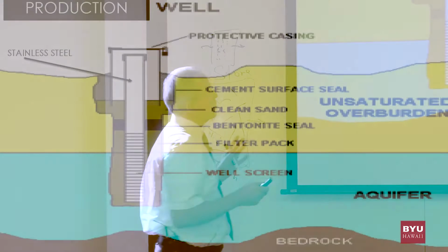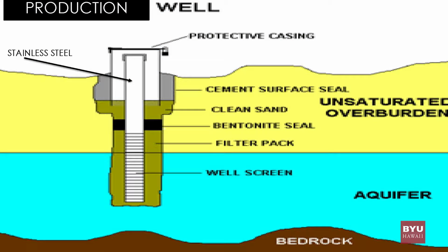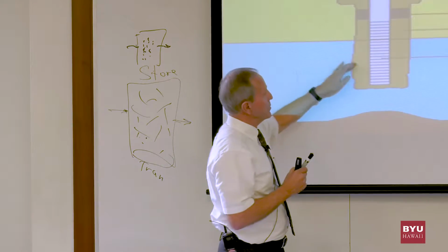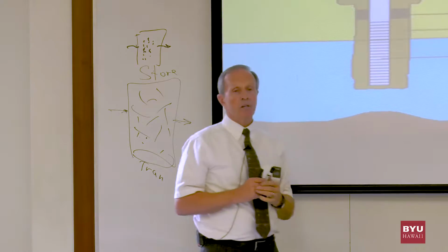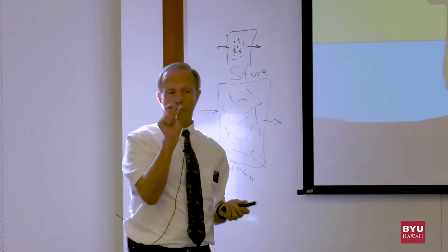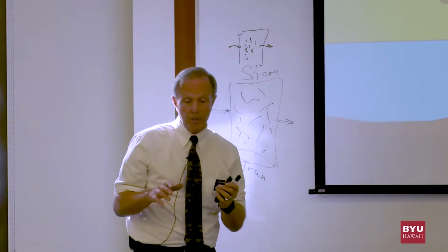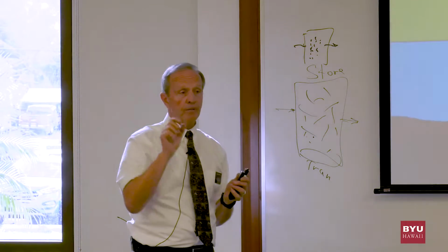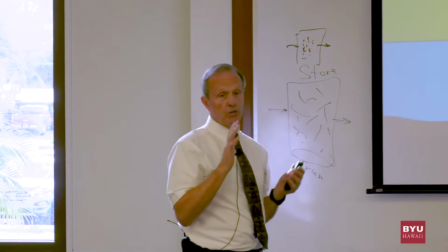When you construct a pump, or construct a well, here again, this is your screening. That's an open part, but it's a metal screen so that the water can come through. It's very, very open, but it also has slots and different things. Now this water is able to come through here. This is solid. When we put a well in at one of these wells, the water was so aggressive, if you put in a great big 16-inch carbon steel, then in 2 years you can throw it away because that water would eat that up in 2 years. Your well casing was gone.